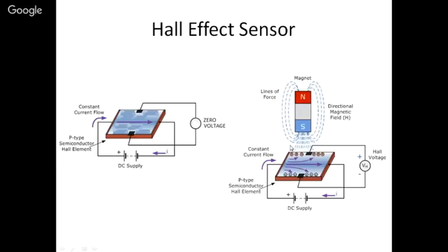When the magnetic flux is amplified, there will again be a change in the voltage. Hall effect sensors, like the inductive sensors, are available as a single piece with all the electronics on it. They are used for proximity sensors, or crankshaft position or camshaft position sensors.